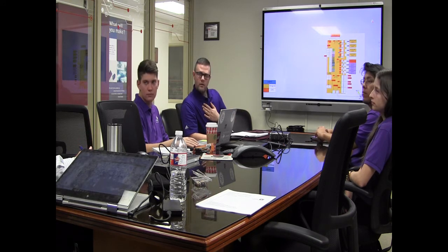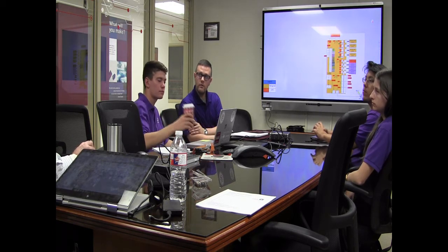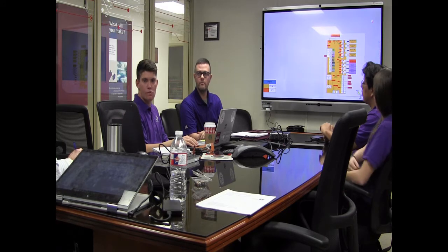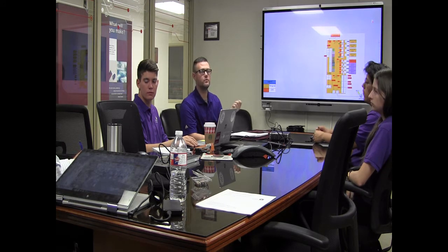And all of that has been connected using RJ11s? RJ12, which is a 6-pin, 6-conductor standard versus RJ11 that's usually 4. But it looks the same as an RJ11. It's fully populated instead of only the 4 middle ones, like your phone or your fax might be. Well, faxes.